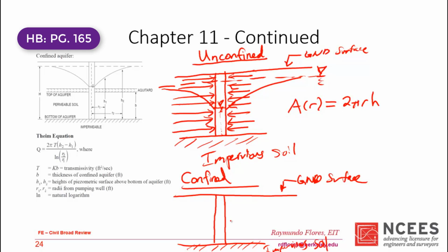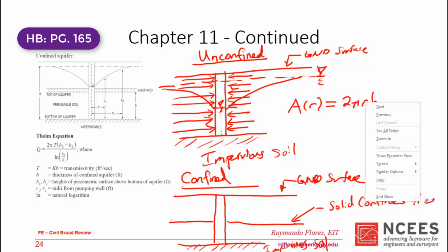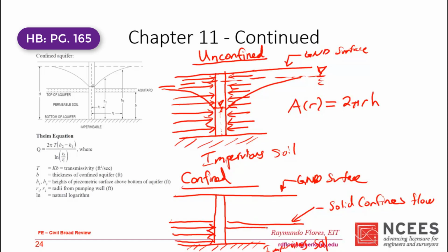And because this is the impervious soil, this is like penetrating. If you have a confined portion of it right here, I'm going to say solid confines flow. That is the same thing as saying that we would expect the flow to be only this way. It might seep through a little bit here, but this is how we're idealizing it. We're idealizing it such that there's no flow here.